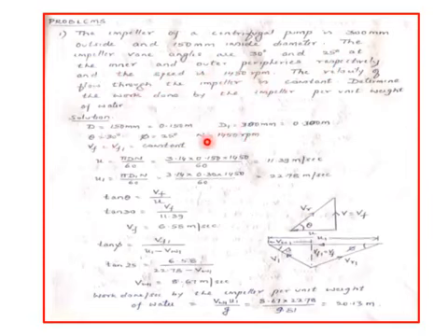Now the vanes are moving at a speed of 1450 rpm, so N is 1450 rpm. The velocity of flow through the impeller is constant, so Vf is equal to Vf1, equal to constant. You can determine the work done by the impeller per unit weight of water, in terms of meters. You know that work done per unit weight of water is Vw1 U1 by g. So our aim is to find Vw1, then find U1 by g, so that gives the work done.